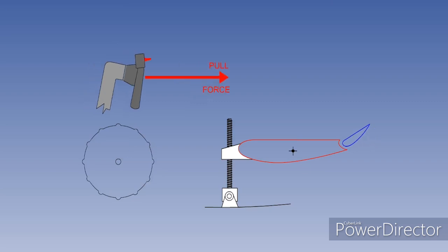Once again, we will consider an aircraft with a forward CG, a nose-heavy aircraft. As before, to maintain equilibrium, the pilot must move the stick aft to move the elevator up. Holding the elevator up requires a pull force. The aircraft is in equilibrium, in trim.